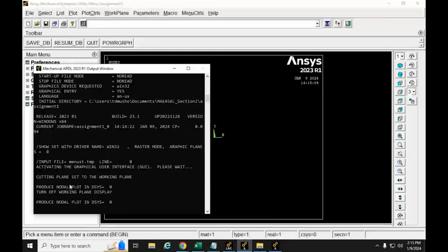One thing you'll notice is that if you look at this output window, the X is grayed out. If we ever somehow close this output window, it'll basically crash ANSYS entirely. So we always have to keep this output window running in the background. One thing it is useful for is if you ever get a no solution, you can look back on this output window and it will give you some details of what potentially is wrong. So just keep that in mind.